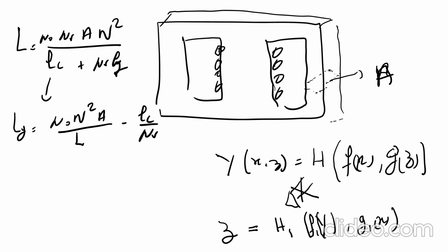If you sweep the cross section, your inductance will sweep also. But in most of the optimization or design cases that I have seen in papers or technical documents, they fix the inductance from the beginning and then change the cross section. That's not the correct way to optimize your inductor.